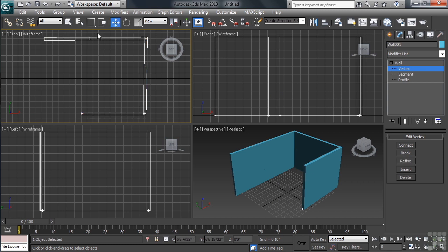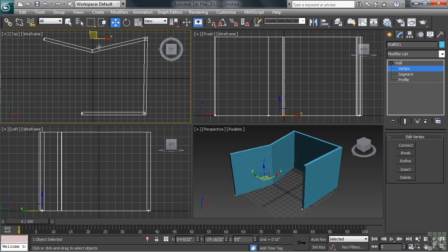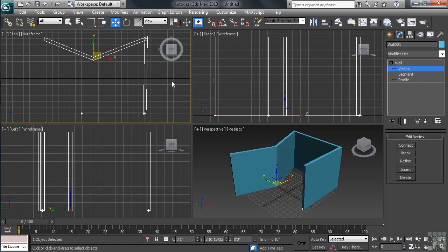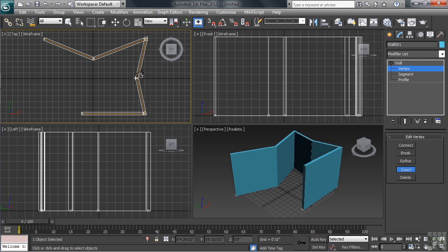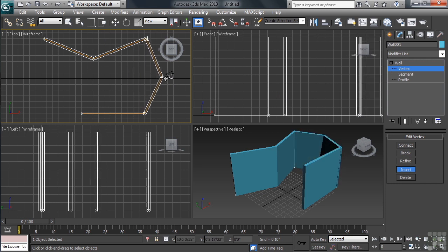That enabling us to then select that new point, moving it to where we'd like that new wall portion to be repositioned. Insert also adds a new insertion point, but with it, when you click, you actually hold onto the existing wall, re-angling it as you move your mouse.